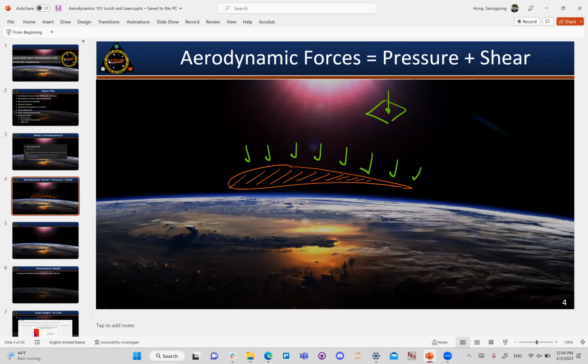This form of pressure includes the pressure that you feel right now, because we're being weighed down by the atmosphere, and the other types of pressure that I'll talk about. So for this airfoil to fly, which side has higher pressure, the top or the bottom? Yeah, the bottom has higher pressure than the top, and the net resultant force is going to point up.